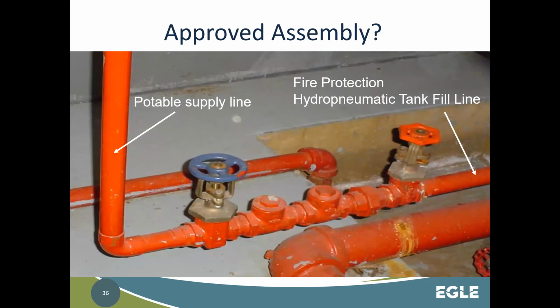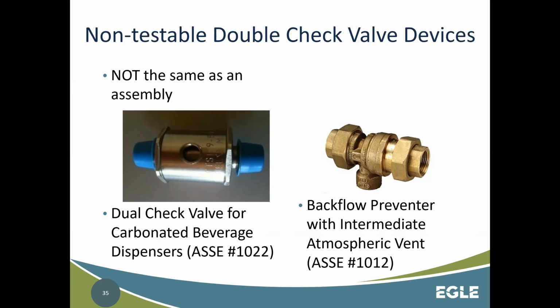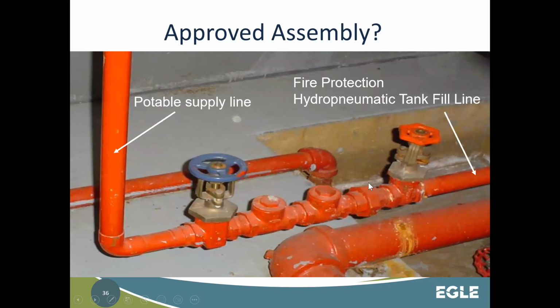Here's, well, that's not picture one. I've got one coming up. These are typically seen on boilers within homes and businesses that are not very large boilers, okay? You'll see these. And how these work is the water flows in one direction. If something occurs, they blow it out the bottom. That's why they're called vented double check valves.